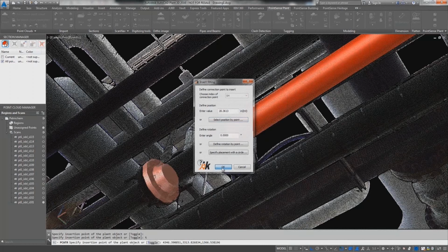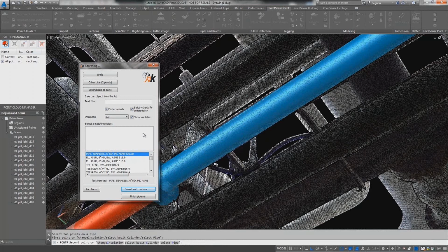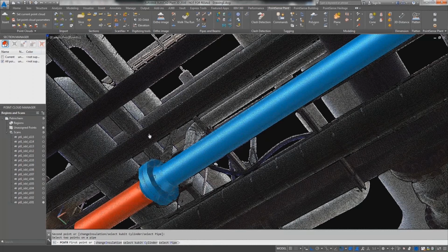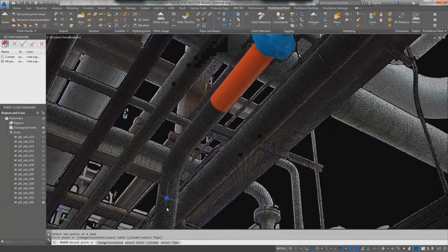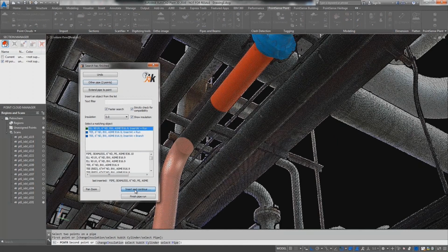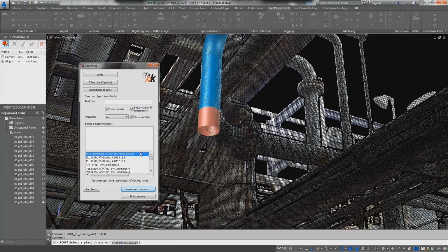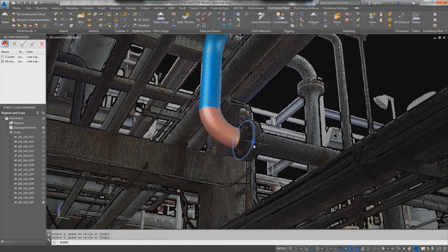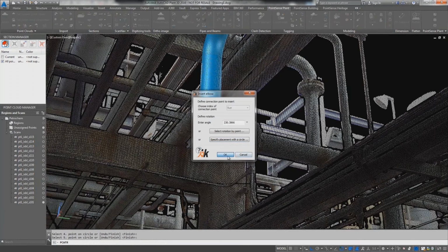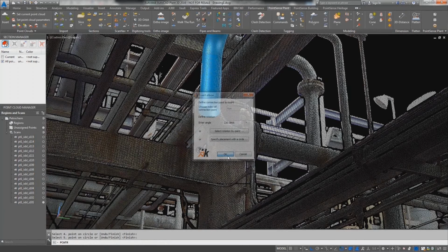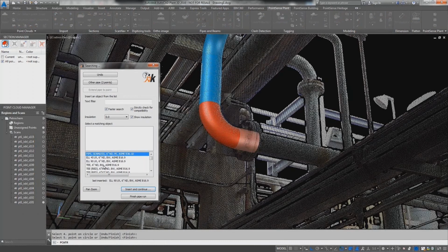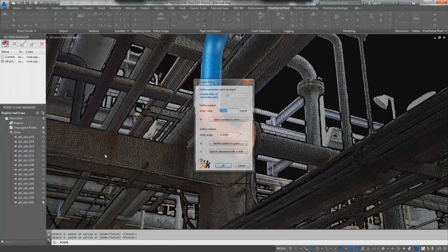So it's user preference. We give you a ton of options, but it's up to you to use what you are most comfortable with. And here I use the traditional other pipe option. It works the same as it always has, probably a little bit enhanced because the resulting cylinder will extract further. Then we're actually using a manual insertion using the specified points around a circle. Now this right here, this is your fallback option. This is when our software can't find it. This is when maybe it's not in the data. But the important thing is you have a way to still get your work done.